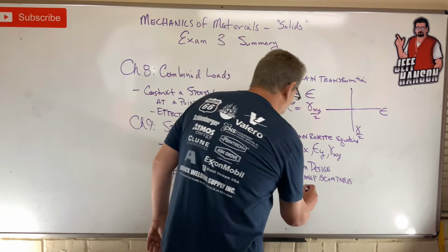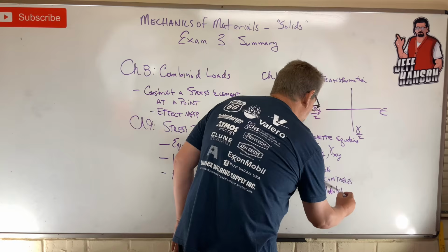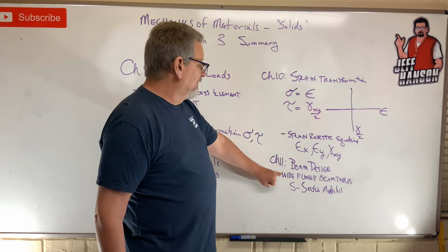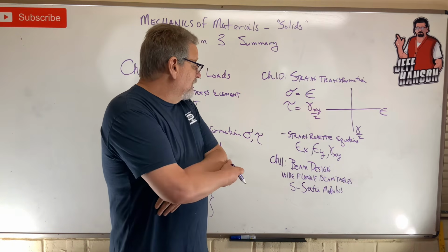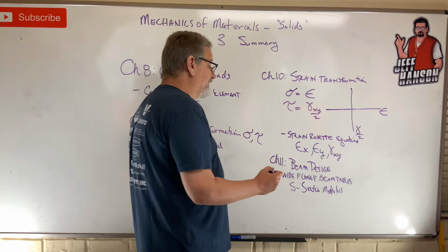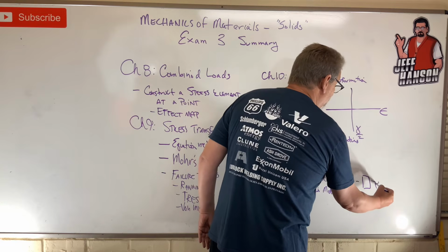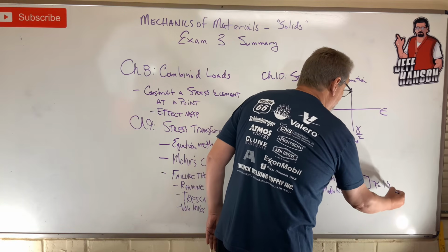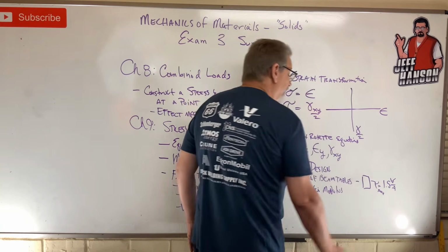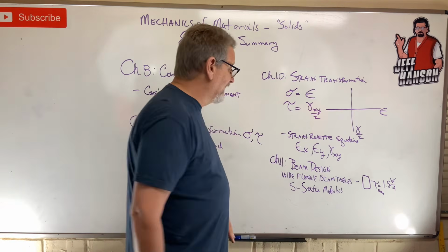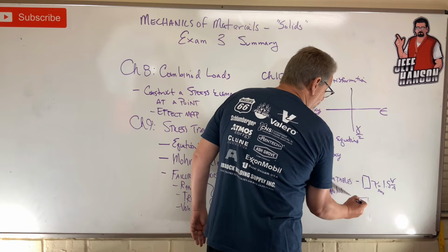Do you remember the section modulus? Section modulus. And that was a thing that we used to look up which beam we were going to use. Okay, so just to select which one we're going to use. There were also two little shortcut methods. One for rectangular beams where we could say that tau max is equal to 1.5 V over A. That was a little shortcut we learned, it works just for rectangular beams. And the other one we learned was for I-beams.